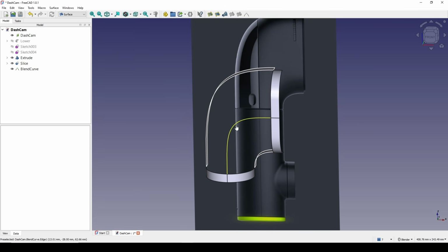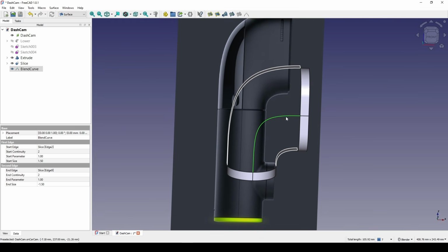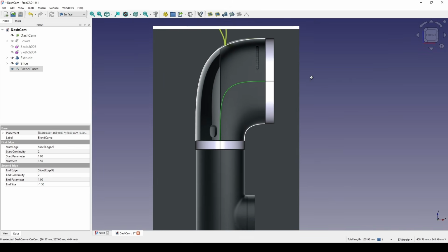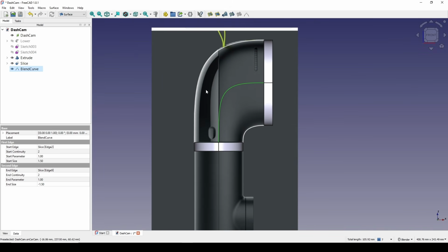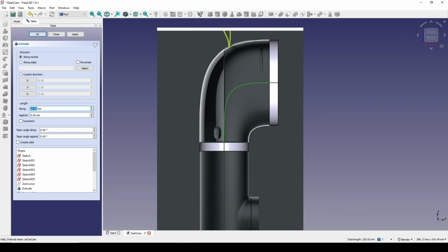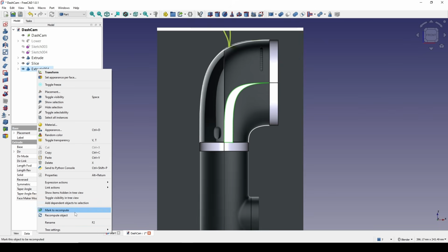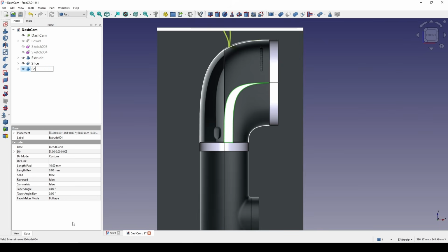And I also want to extrude this one to have surfaces to control the tangency. First, I will extrude this one to the right and use that for the surface on the left. I click on the plane curve, go to the part workbench and extrude this one to the X-axis, positive one, and click OK. And rename this one to far left.